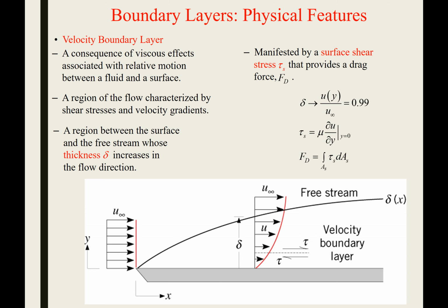As soon as it encounters what's called the leading edge of the table, the flow is going to start experiencing the viscous forces caused by the table. So we'll start to see a boundary layer form. Our flow, initially the very bottom, quote unquote, layer of fluid will encounter the table, and it'll be dragged down by the table. As it moves along, that bottom layer of fluid is going to grab onto the layer immediately above it.